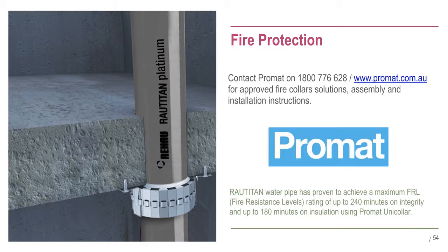For the protection of penetrations through fire-rated walls and floors, fire collars are available from manufacturers such as Promat. Contact these manufacturers for the latest test reports and technical data and to confirm the fire collar's suitability for a specific installation.